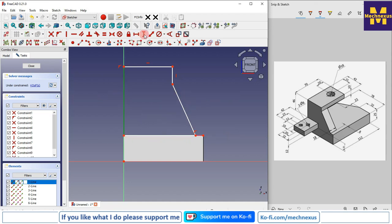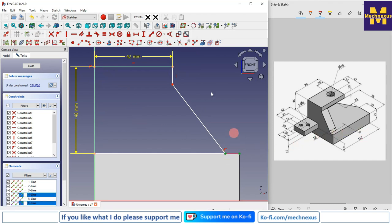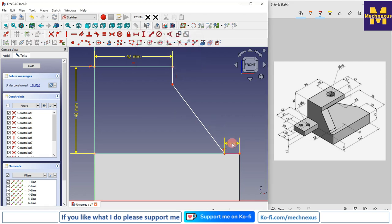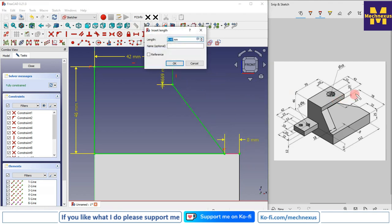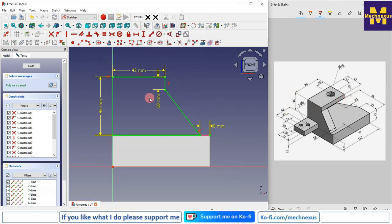So this one is a 46. Move this point to the downward side. Now this is the 42, and this point to this point is 8 mm. You can parallelly see the drawing for the dimensions which I am giving, and this is the 10 mm which we can see here. Give the 10, and this is our fully constrained sketch.